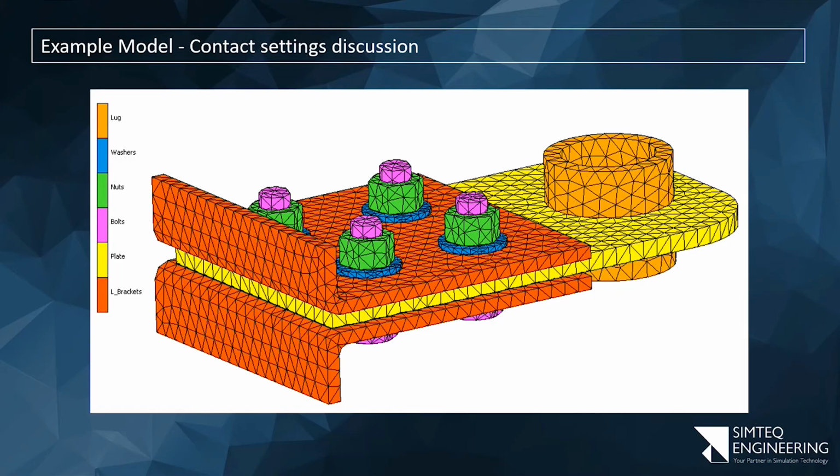And then maybe the last one, I just want to find out if there is a way that you can determine, let's take for instance, now it's difficult to see which one has the finer mesh between the bolt and the nut. Is there a way where you can see maybe the number of elements that can tell you which one has a lot of elements that would be used to determine which one has a finer mesh or not? It's actually easy to find the number of elements, but that doesn't tell you much because a larger part with larger elements can have the same number of elements.